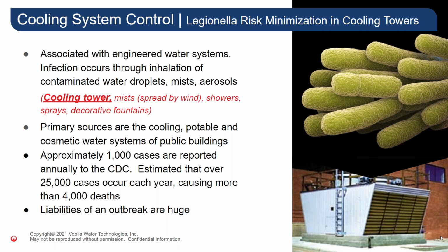This bacteria does, however, pose a risk to humans that inhale water droplets containing Legionella. So individuals with compromised health, weakened immune systems may contract legionellosis, a type of pneumonia, or Pontiac fever, which is a little bit less harmful illness. But for some folks, legionellosis can be fatal. Since the cooling towers intentionally create little droplets of water as the water cascades down the tower, plus fans push or pull large quantities of air through that water, a tower with Legionella may have aerosol with Legionella in it, and those droplets can be breathed in by personnel working in and around the tower or downwind.